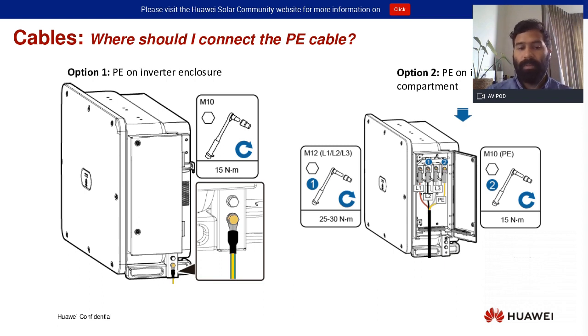Normally, I would say, in my experience, the most common is the external solution, and it will also perhaps be the most practical and the best solution, because you are connecting directly the inverter to the module structure, which normally must be grounded. So this will be the easiest way to do it. But you can also, for example, do it through a 4-core cable with a PE, use the PE inside the terminal, and then go to the equipotential grounding that you have on site.